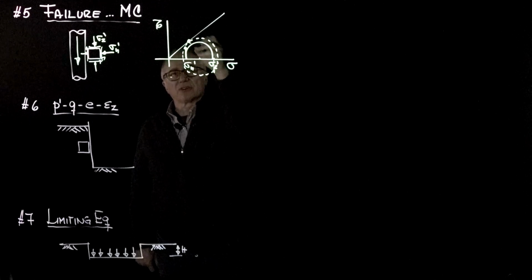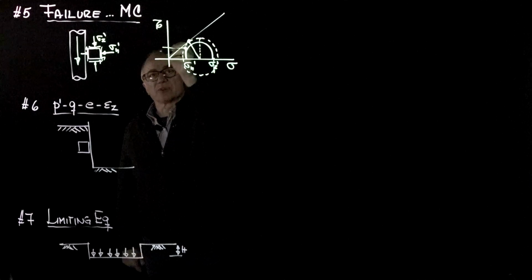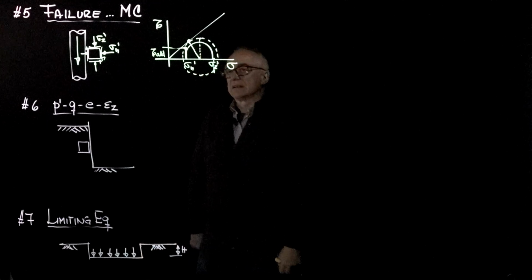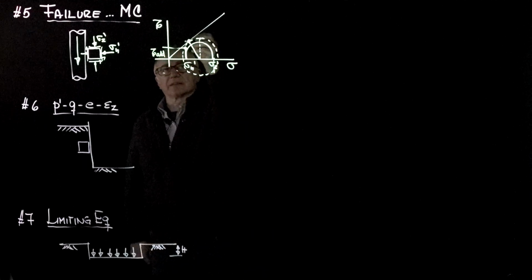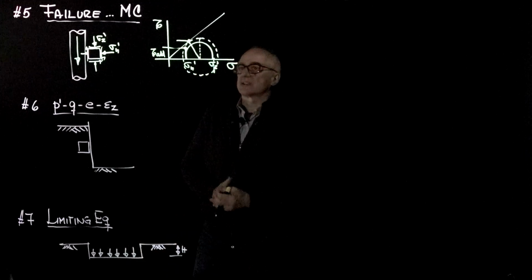So if I draw a radial line, this is normal, and that amount, that shear, which would be probably this maximum shear here, it is the maximum shear in the circle, is not the amount of shear that you can add. The amount of shear that you can add is this piece here on the side. So this is what can be tau add. That is the amount that can be added, even though the tau at failure is this amount, but the system already has an initial shear.